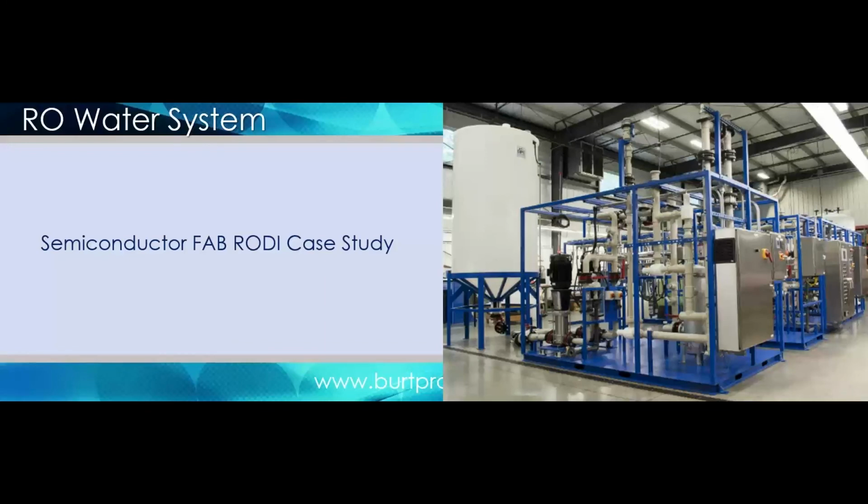So, Mark, I had a question regarding the loop sanitization itself. What's involved in that process, and how do you gauge how often you need loop sanitization to be performed? So loop sanitization is done a couple of different ways. Really, you're either going to do it by a chemical or by a temperature. The chemical method is either going to be done with ozone or a peroxide-based solution, and the temperature method is either hot water or steam.